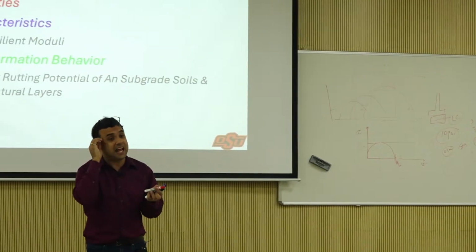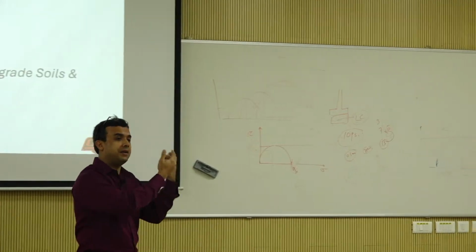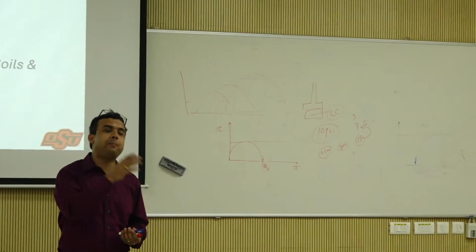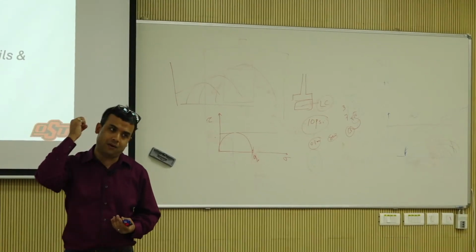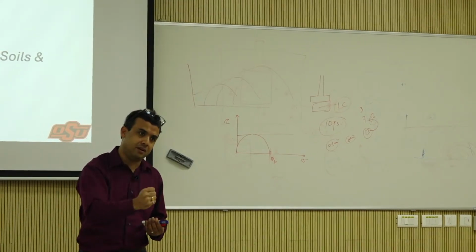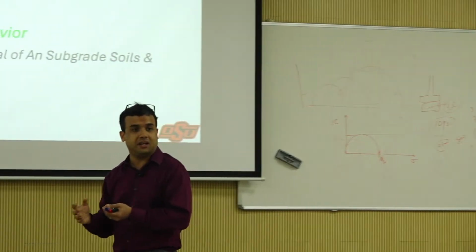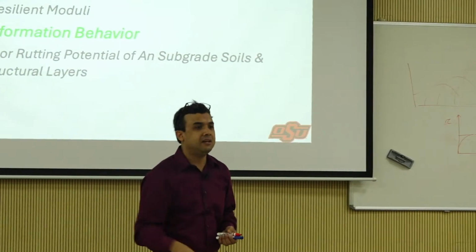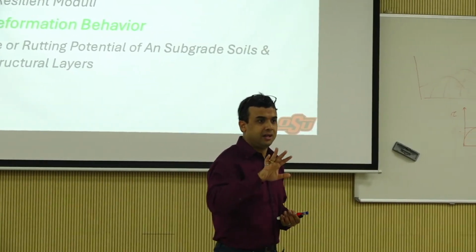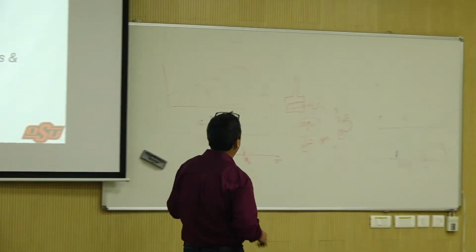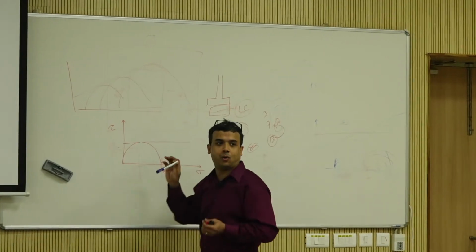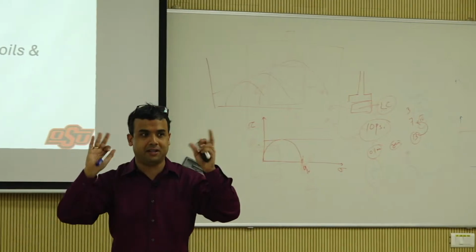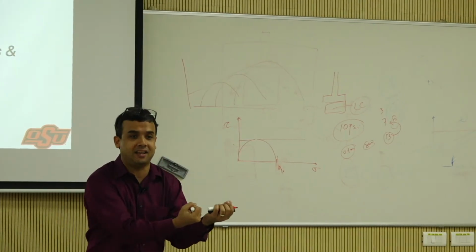But the test can be, a triaxial test is deformation controlled or strain controlled. You say that I'm going to apply 1% strain per minute, and then I will just keep pushing this sample. Whereas when we go into modulus testing, you will see that I'm going to apply a 10 psi load pulse every 0.1 seconds. Because it's all triaxial, I wanted to give you this background on what is load stress control versus what is strain control. So just remember that. What are you asking the system to do?